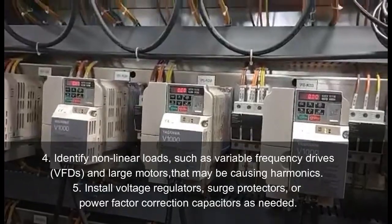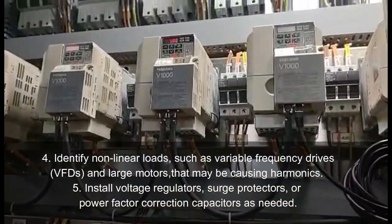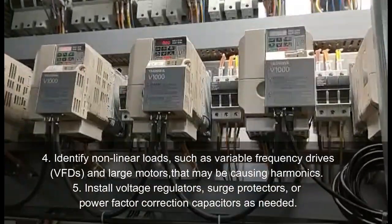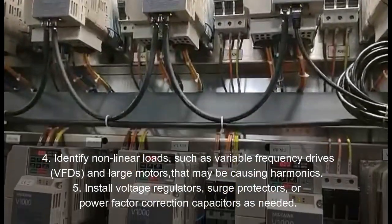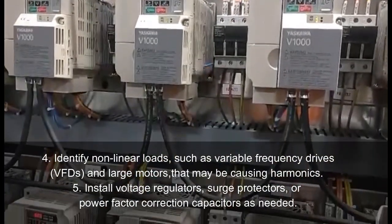Number 4. Identify nonlinear loads such as variable frequency drives, VFDs, and large motors that may be causing harmonics. Number 5. Install voltage regulators, surge protectors, or power factor correction capacitors as needed.